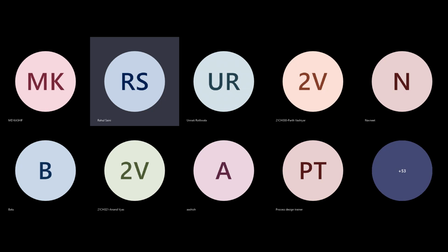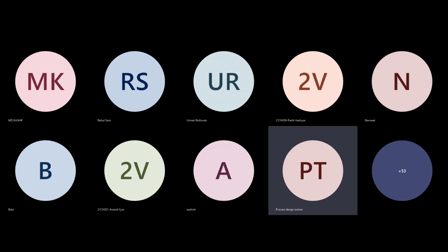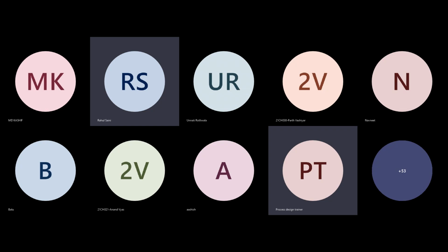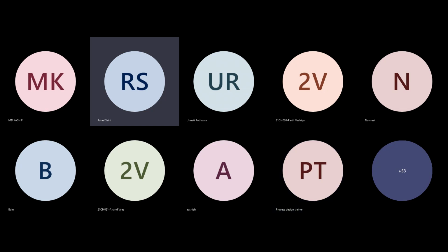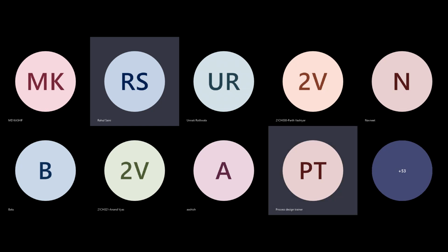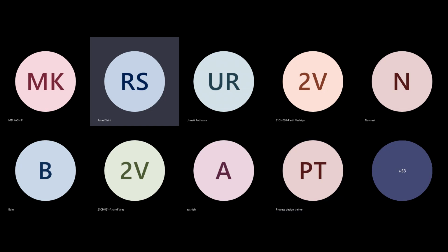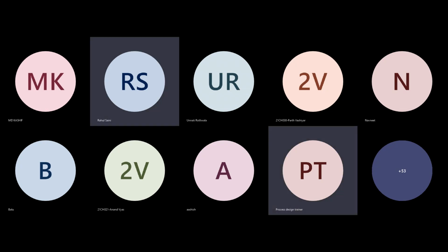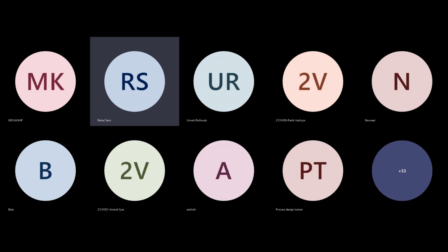Okay, I was thinking the same. You should study the MOC. Yes, study if the correct MOC is installed or not, and what type of corrosion it actually is. The construction material, the MOC, is 317L.